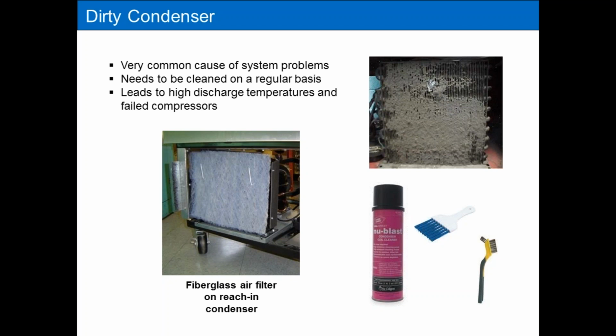The only issue with them is that they're pretty pungent. They smell. So you've got to give a heads up to the people in the kitchen that you're going to use a chemical that has a pretty strong odor to it. It may be offensive to some people, but it's definitely better than kicking up a dirt cloud by using compressed air. What I normally do is brush it first with a good brush, get all the heavy dirt off, and shut the unit off. Generally I don't apply the cleaner with the unit running. Shut it off, spray it down, leave it set for maybe 5-10 minutes, and plug the unit back in. If it's really not that dirty, that is a pretty effective way of cleaning those coils.